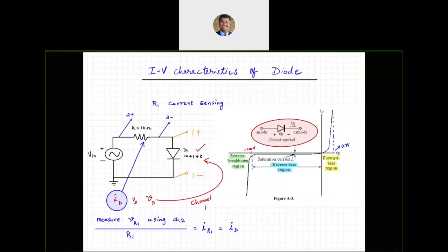VD wouldn't necessarily be 0.7. Well, for all theoretical purposes, we are going to have to stick with some value where everybody can agree that this is going to be the value where the diode turns on. So that value for the diode is going to be 0.7 volts.